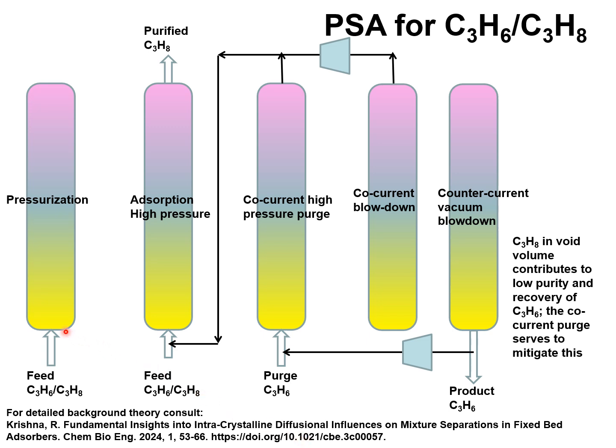The candidate adsorbents that are suitable for kinetic separations are Chabazite, CAU-7, that practically exclude propane from the pores, allowing high purity propene products to be recovered in the final vacuum blowdown step. In today's presentation, I'm going to talk about separation of propene-propane mixtures using ZIF-8.